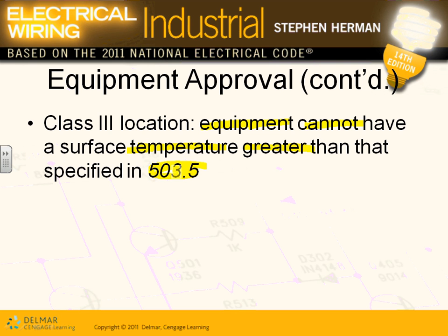If you go to 503.5, there is a table, and it limits the outside temperature to certain values so as not to ignite the surroundings. For equipment not subject to overloading, you have 248 Fahrenheit for equipment such as motors and so forth. So there is a temperature limitation.